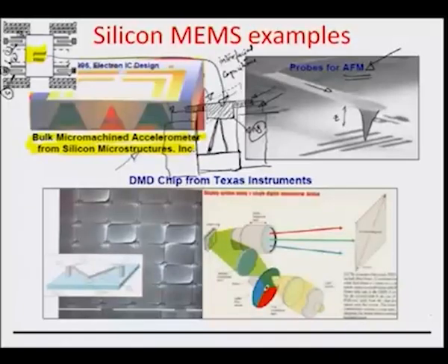So, therefore, if suppose I were to monitor these small valleys which are present over the surface, I would simply scan this cantilever on the top of these valleys, and wherever there is a valley, and if we have some positive pressure onto the top of the cantilever, it would go into the valley, and there would be a displacement in the negative z direction. And if we can record that, we can really take all such data points and reconstruct the image of the surface based on some of these points.